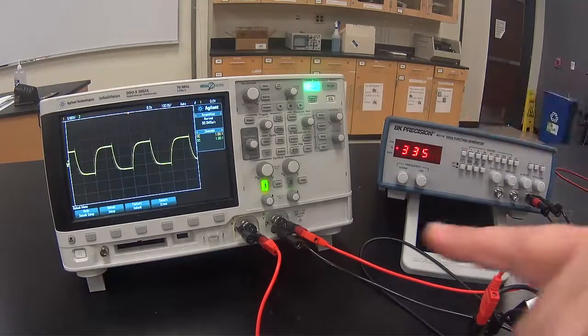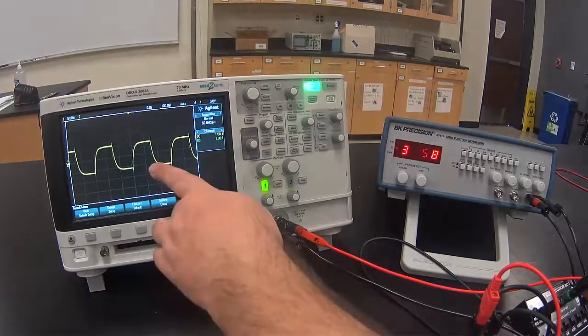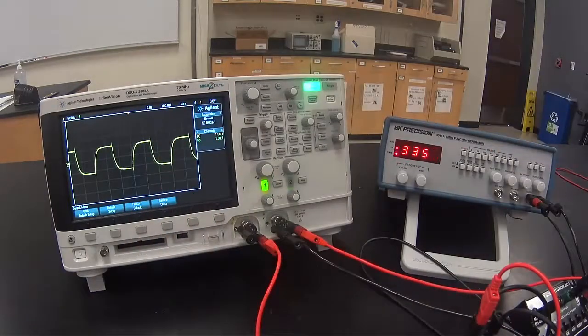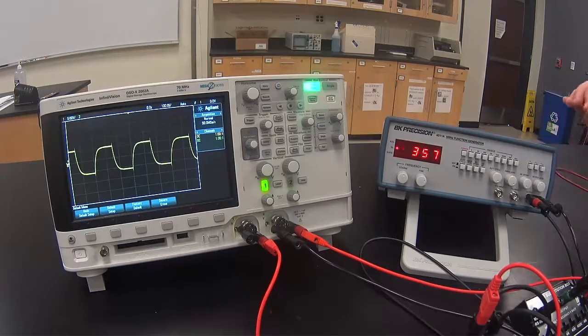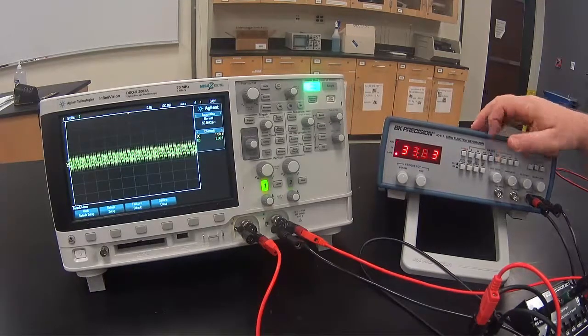Now the frequency of the function generator is quick enough to display a few periods at the default setting of the oscilloscope. Notice that the shape of the curve hasn't really changed. What we are observing is the voltage across the capacitor. We are using the square wave on the function generator to mimic an on-off switch for charging and discharging the capacitor.